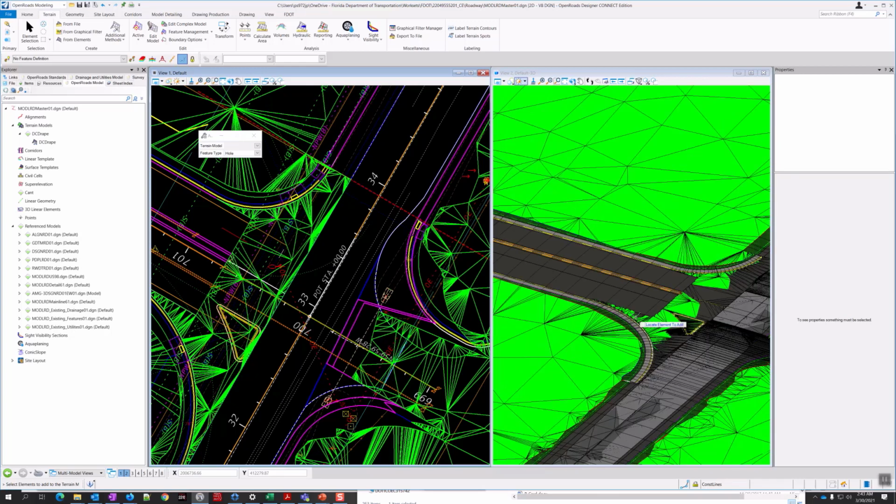So it's not ideal. Another thing we can do is change it and see if that makes a difference. We could edit it manually. It's likely it's not going to change when you're at the point of visualization. I could just go in here and delete these triangles in the middle. If you go under feature management there, you have the option to change feature type.